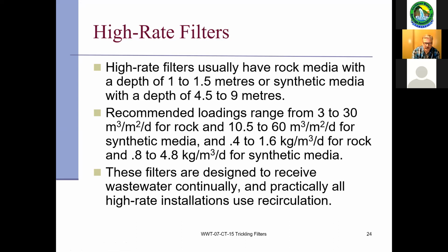The rock is only 1 to 1.5, and synthetic media is 4.5 to 9 meters. That's a huge difference. Why do you think they have that difference between the two medias in a trickling filter? Any thoughts on that?